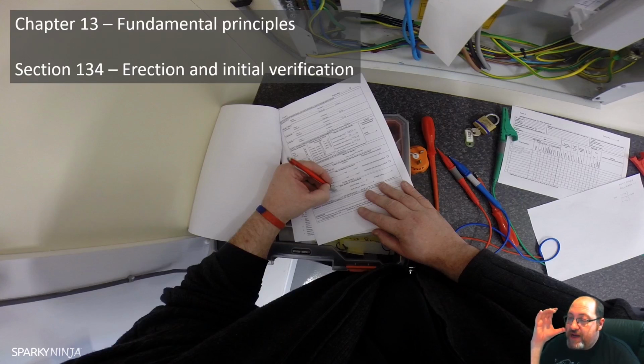The characteristics of the equipment as determined in accordance with section 133 shall not be impaired by the process of erection. So the erection of the equipment shall not compromise the requirements of 133. Conductors shall be identified in accordance with section 514, so we'll get there later. Where identification of terminals is necessary, they shall be identified in accordance with the table in 514. Every joint and connection shall be of proper construction and will have consideration to conductance, insulation, mechanical strength, and protection. So they'll be suitable.